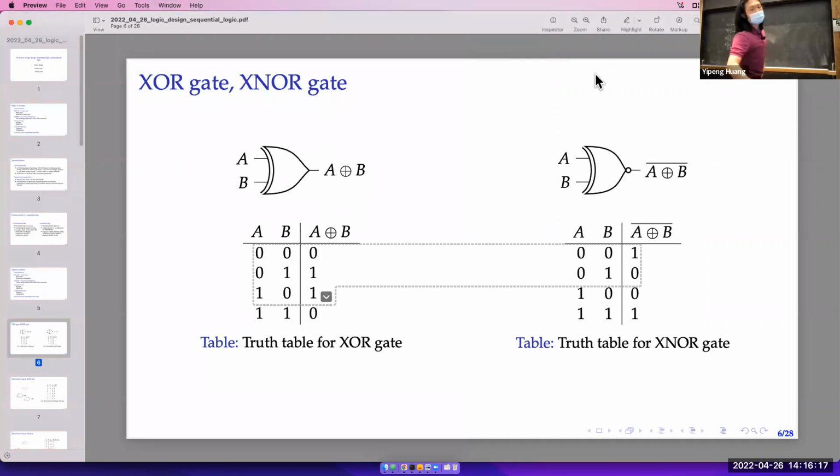I think I need to draw this more stylistically. The XNOR gates have this wavy design here. A1 and B1 go into the same XNOR, and then A0 and B0 go into the other XNOR gate. And only if both of these are true, using this AND gate, then equals is true.